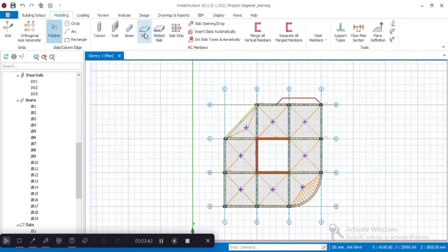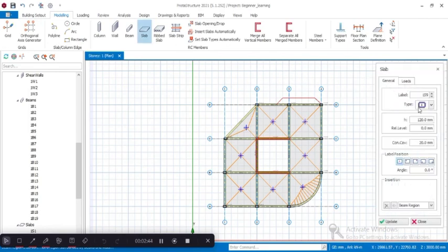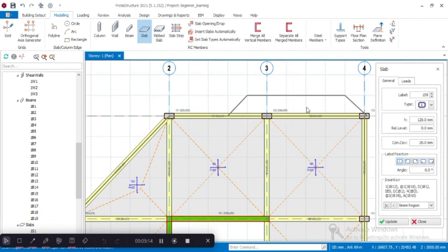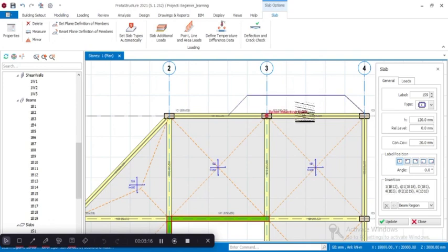Now click on slab icon. So the type one is still selected. So in insertion we'll be using, okay, beam region is selected. So click anywhere within the slab edge. Make sure that it's showing the line before you click on any points, to show you the path where it's going to be. Now click on it, and our slab will appear. So that will be a cantilever slab.